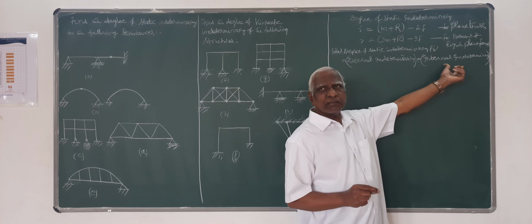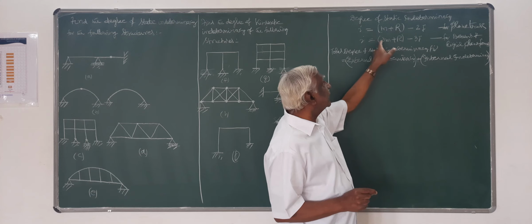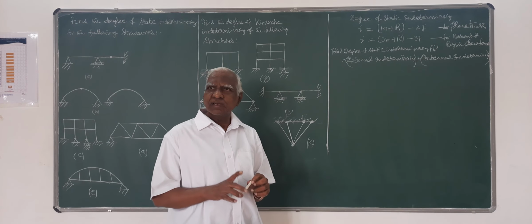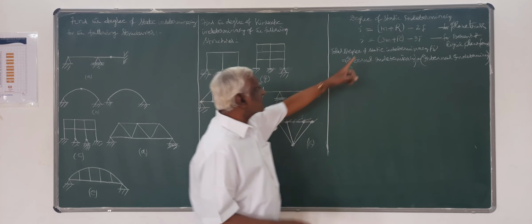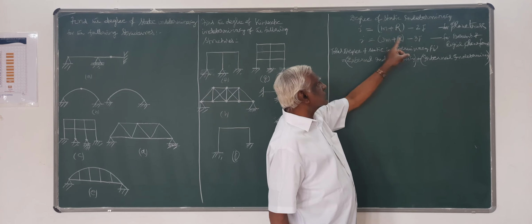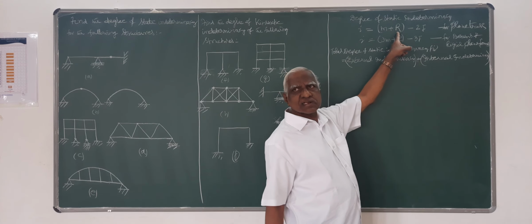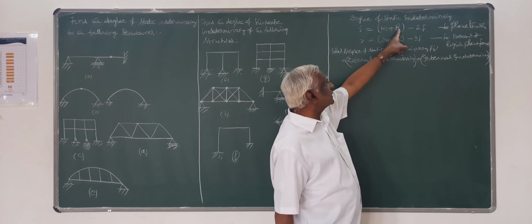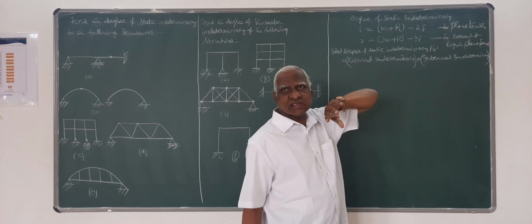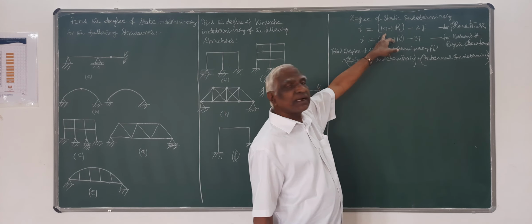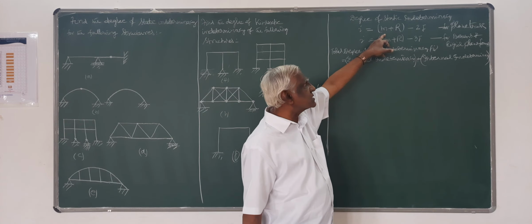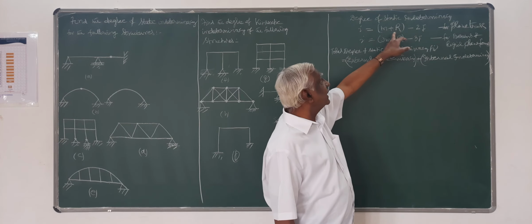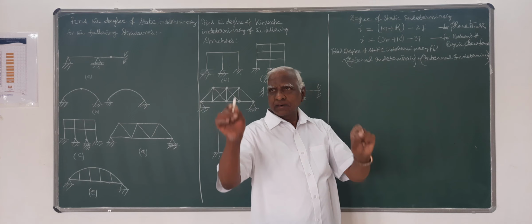And internal indeterminacy is the number of unknown internal member forces which you cannot determine by equations of equilibrium alone. Here the unknowns correspond to internal forces as well as external support reactions.